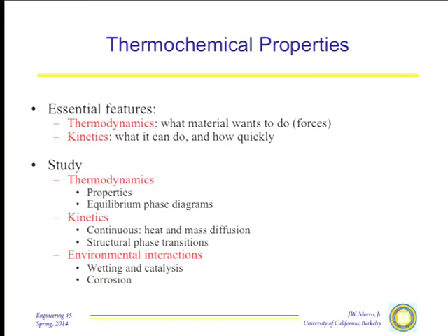In fact, virtually all of the processing of materials involves a rather simple thing, really. You bring the material into a situation in which it wants to change, in which there's a thermodynamic driving force for it to change. You let it start changing. You use kinetics to control the path by which it changes and how fast it evolves along that path. And then when you get it into the situation you want, you quench it or otherwise use the kinetics to bring the transformation to a halt. Virtually all materials that are used in engineering are trapped in metastable states to achieve the microstructures and properties you want. And they are intentionally trapped there. And the whole art of processing is using the thermodynamics to force the material into some evolution, using the kinetics to control that evolution, and eventually to bring it to a stop where you want it to quit. And we'll see examples of that all the way through now.